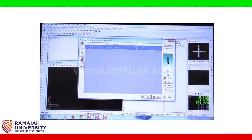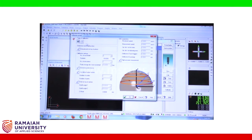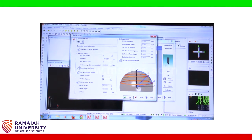Now before starting the measurements, one has to calibrate the probe and see that he is having minimum error in the diameter of the probe. So let us start the calibration process. So I am pressing the calibrate. In the calibrate, you can see lot of options. As of now, we are having the master ball diameter, which is 19.9293, which will be used as a master to measure the probe, and we are going to use probe factors as 5, that means 5 contacts. So I am going to say OK.